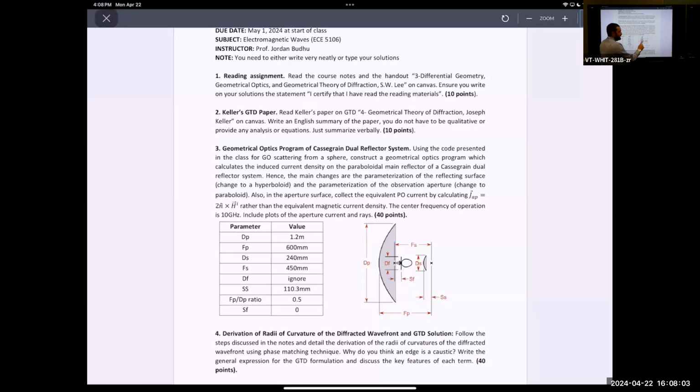So now this focus, I put a point source there. It radiates to the subreflector, reflects off the subreflector. As soon as it reflects off the subreflector, it looks exactly like it was emanating from this focus behind the subreflector by nature of the way the optics work. So it'll radiate here, reflect, and it'll go to the main, and then you'll calculate the induced surface current on the main. And then you can integrate that using physical optics if you want.